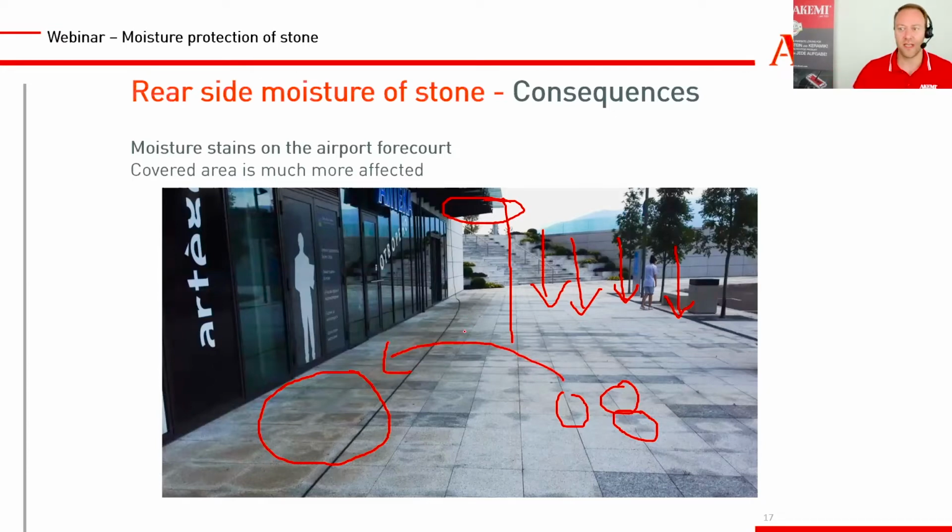And this we often see under carports or other areas which have some roofs and are connected to an area which has no roof on top of it. The stone installation underneath the roofs is usually much more damaged than under the free sky. So what happens is a little bit of physical chemical reaction underneath. Humidity always tries to evaporate where it can evaporate faster. And if it's constantly raining here on the right side, it will not evaporate as fast here. So it tries to evaporate here and then it brings up all of the minerals and salts.